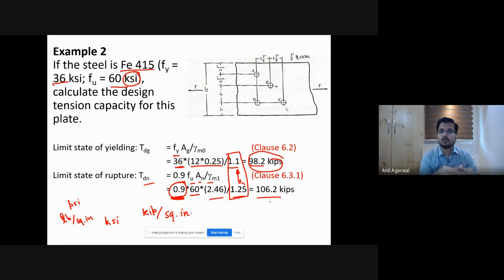But when you talk about rupture, you make six identical plates, you keep the entire fabrication process identical, but just have six different people do it, or get it done from six different fabricators, and test them. You will see that they give a very similar yield strength, but very different rupture strengths. You follow that?